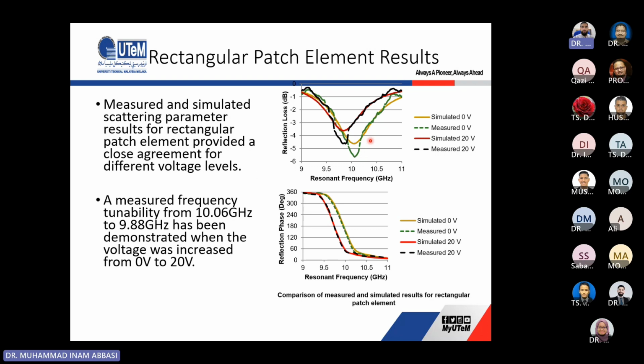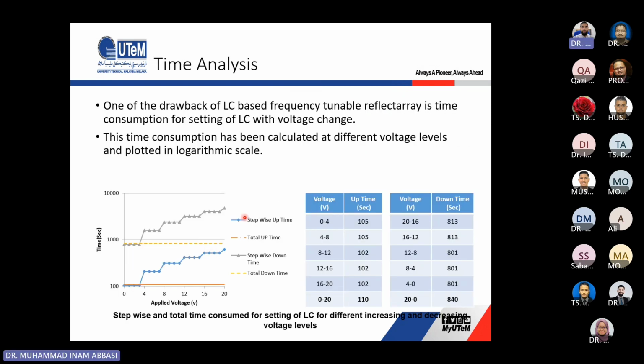So these were the results for the liquid crystal based designs, and we can see the phase. We can also move from one point to another point. So this is how we design reconfigurable unit cells for reflectarrays using liquid crystals.